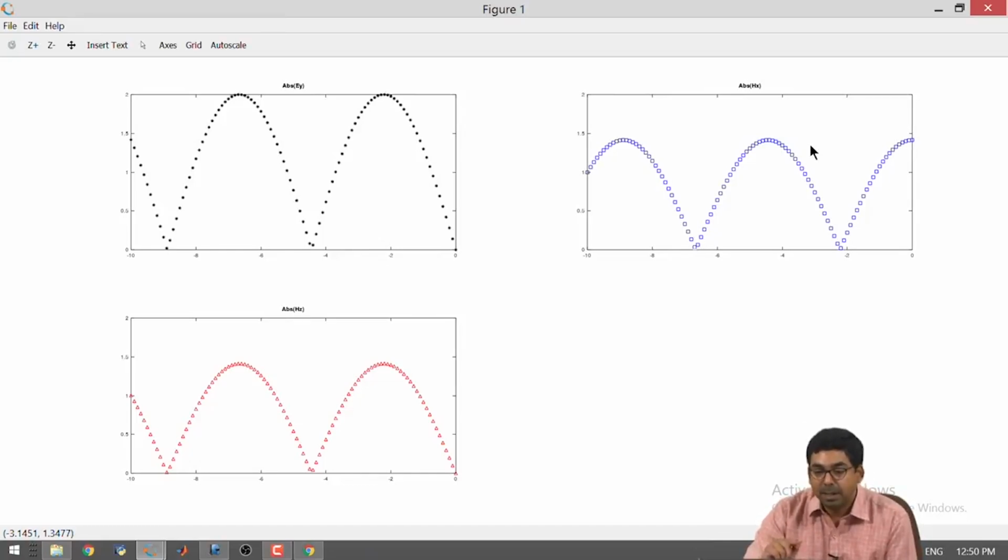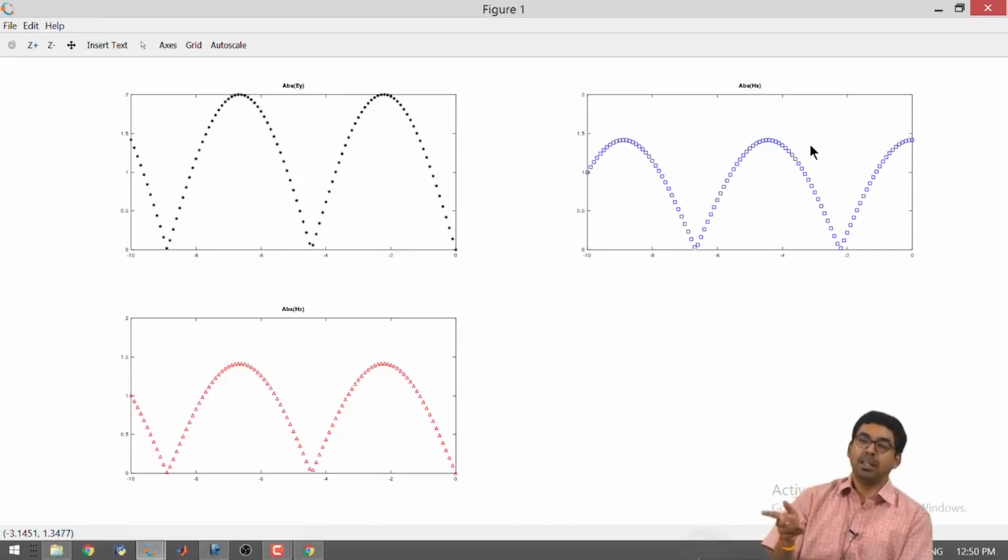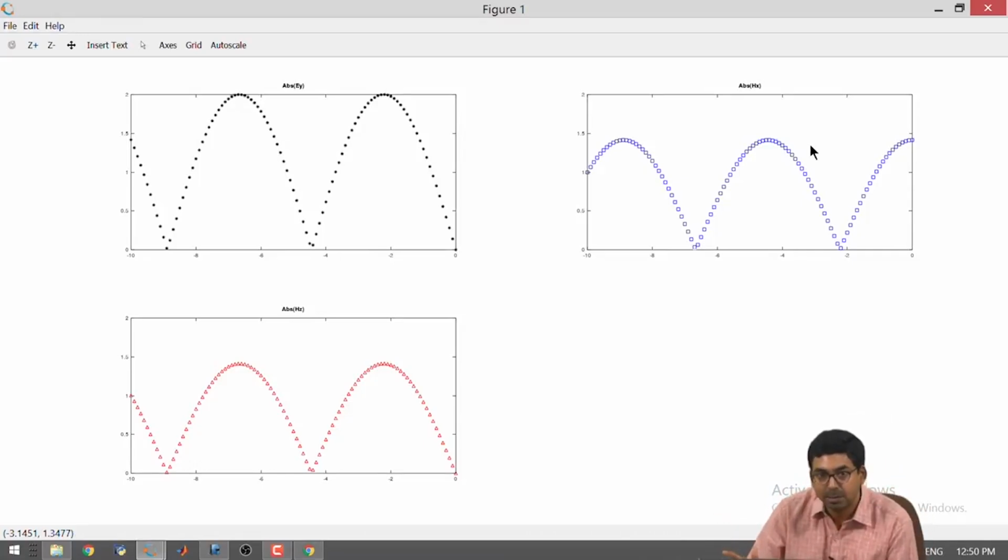And when you have Ey crossed with Hx, since the electric and the magnetic fields are out of phase by 90 degrees, you do not have a power transfer in that direction. It is very similar to the case of inductors and capacitors in circuits, where voltage and current are out of phase by 90 degrees, so inductors and capacitors do not consume any power. It is a similar case. So, I think now you have a tool. There are also other inferences one can make.